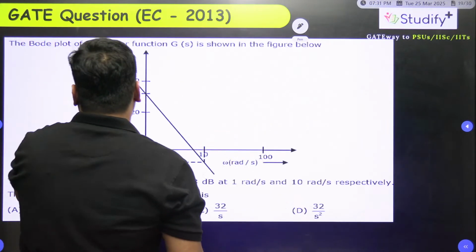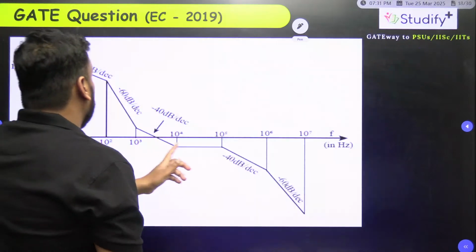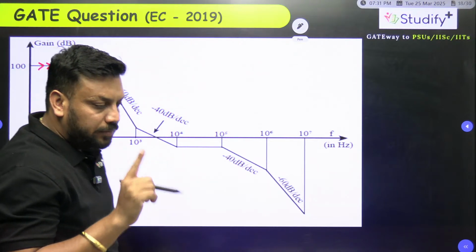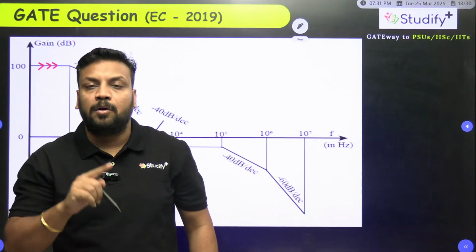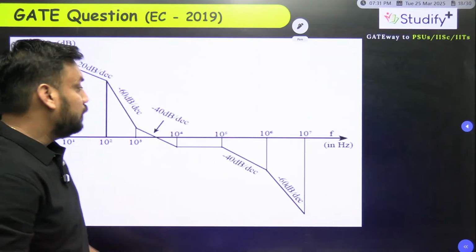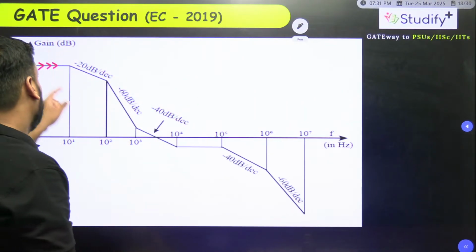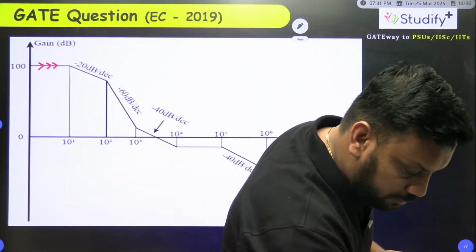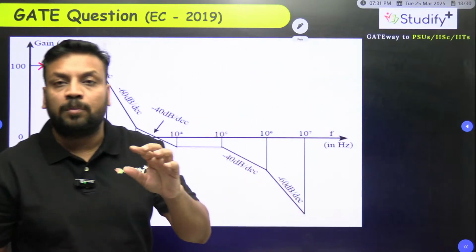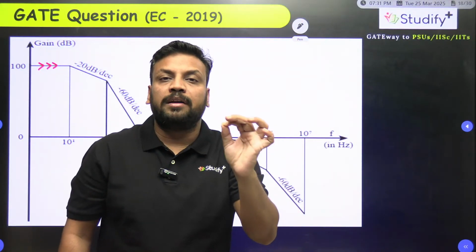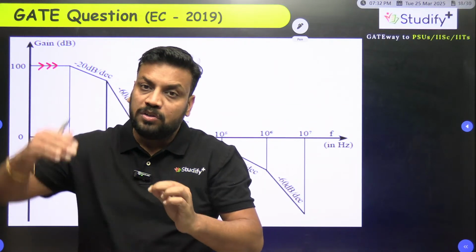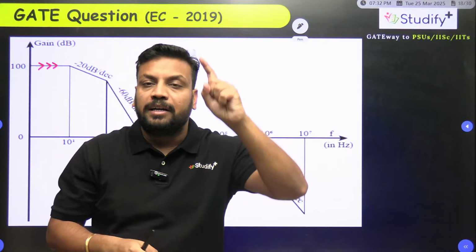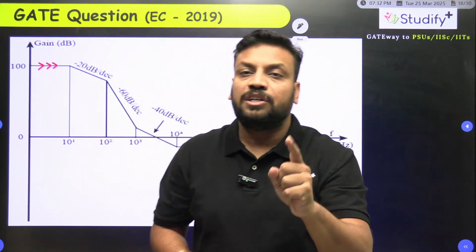चलिए, so फटाफट से start करते हैं हम ये. So ये question है, फटाफट से tell me what is the initial slope, guys? Initial slope is 0. By observing the initial slope, it will provide the information about poles and zeros at origin. तो आप बताओ poles and zeros at origin पे, यहाँ पे this is a straight line. So in the straight line there is no initial slope. It means the initial slope provides information about poles and zeros at origin. Because initial slope 0 है, इसका मतलब कोई भी pole और zero origin पे तो नहीं है. It means there are no poles and zeros at origin.